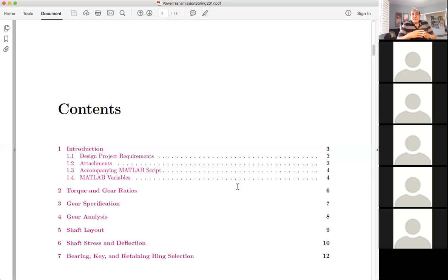And also we have to determine the twist angle from the torques, and find out if the angle of twist is also consistent with the design requirements. So that part of the shaft analysis we can do right away. Then the last part of the shaft analysis is to determine the lifetime of the shaft due to fatigue or static.